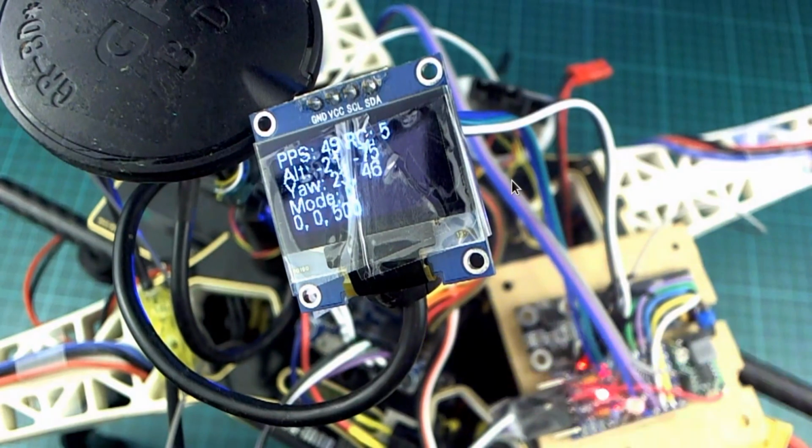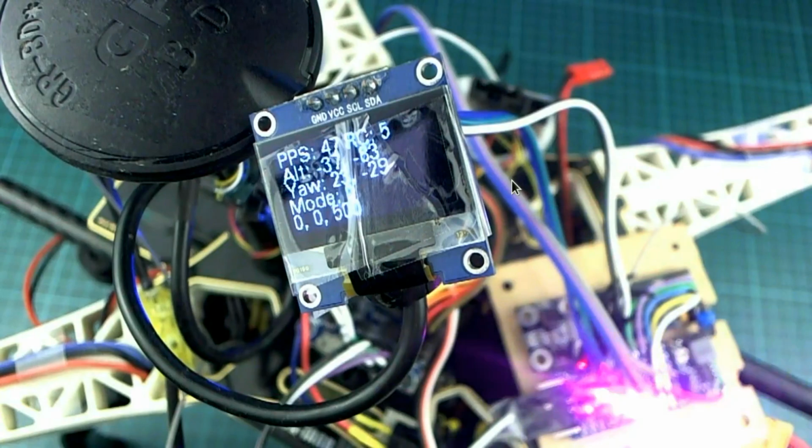And the reason that we ended up with this is because the mode it's set to use at the moment is overhead, which means that it's going to position itself horizontally at the same place as the follow me tag, but above it. And this 5 meters is just a safety value, because since the quad and the tag are going to be in the same place horizontally, they can't also be in the same place vertically, otherwise, you know, it might be a bit painful. So that's why it's 500 in this case. But these numbers will change a little bit depending on what kind of mode you are using.